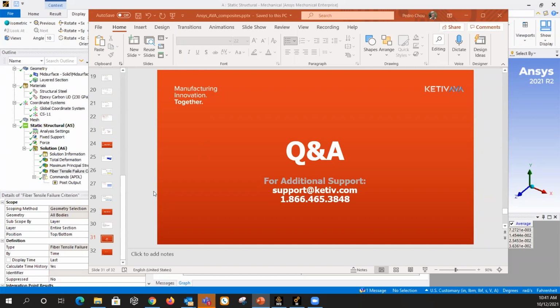You have the A, B, and D matrices, which would be the stiffness in extension, bending, and shear, and then use all those terms to assemble the element stiffness matrix. So basically, the information that you use for each layer will calculate the stiffness for each layer, and Ansys will combine the stiffness of every layer to give you just a single element stiffness matrix.